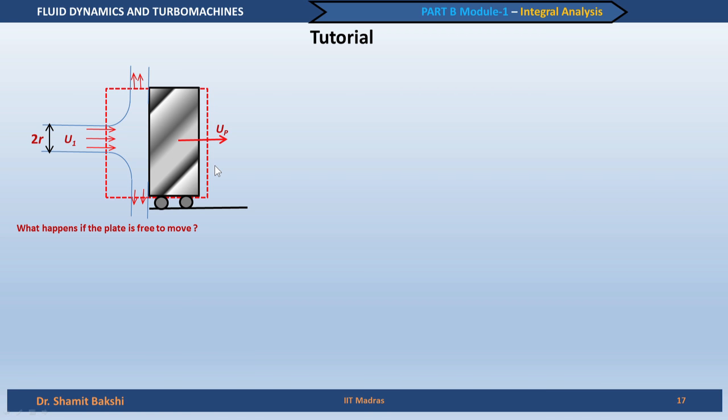The difference between this case and the other case is that here the control volume is moving, and not only that, it is not moving at a constant velocity. So, it is accelerating. So, we take incompressible flow and we see how we can apply the linear momentum conservation equation for an accelerating control volume. The reference frame, as we are saying again and again, is always fixed to the control volume. So, this is a problem with a non-inertial frame of reference. So, the momentum conservation can be written in this form.